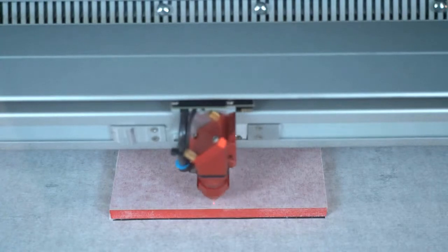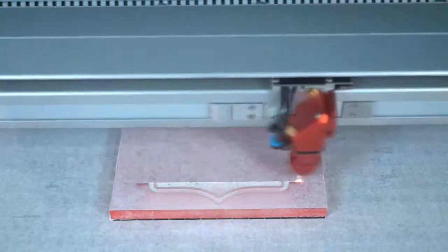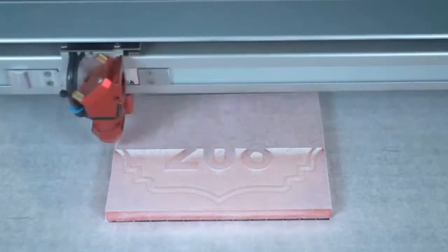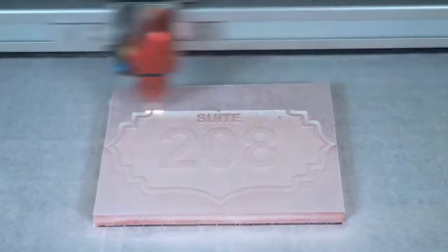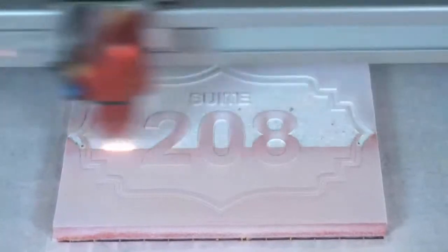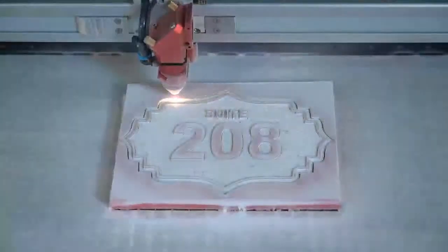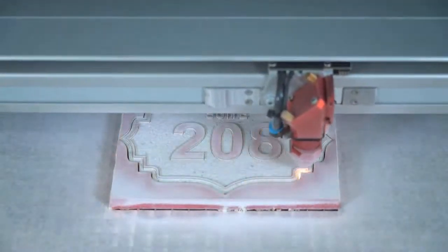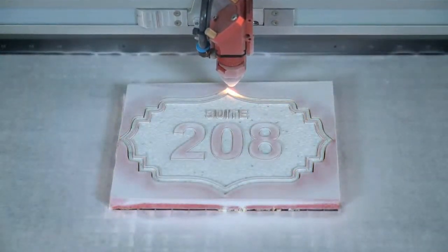And I've got a black outline with a red cut line and then a blue outline around the characters. The blue outline gives me a nice vector and kind of a sharp edge, and so the laser will apply a power setting. This is a high-powered application, so I'm going to engrave it with 3 passes. And each pass is going to perform a little bit more depth into the material, so I get that nice raised letter solid surface sign. And then I go ahead and cut it out.